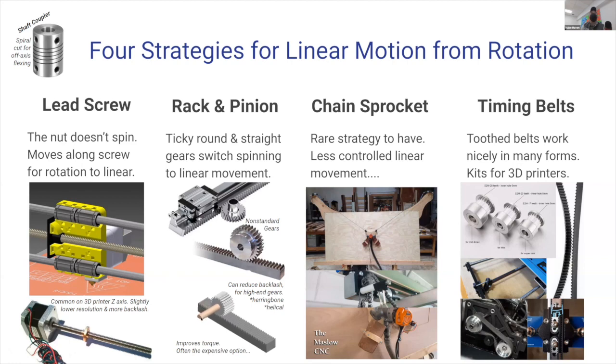The Gerber does not use this. The Gerber uses just lead screws. But the ShopBot, which is another type of machine, sort of in the same family as the Gerber, uses rack and pinion gears. And I would be shocked if the Tormach didn't use some of these also, because they're just a good, strong way to transfer power back and forth. They do pretty much serve as a huge pinch risk. If you ever got your finger in there, you'd have a big problem.